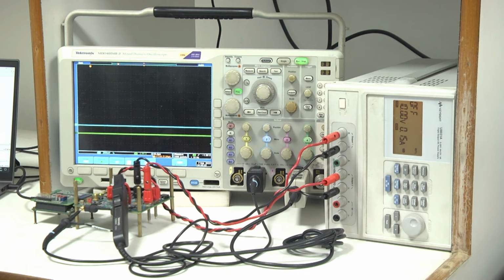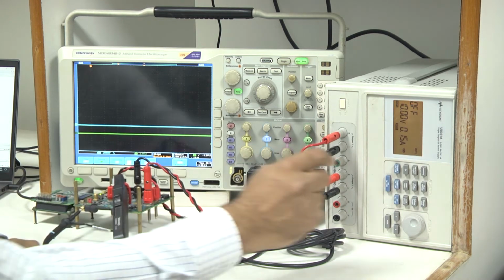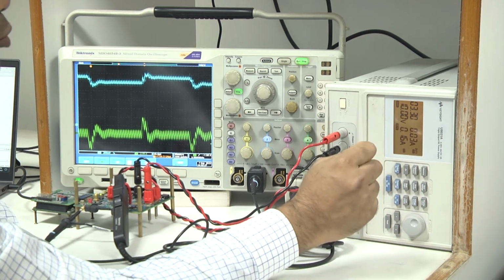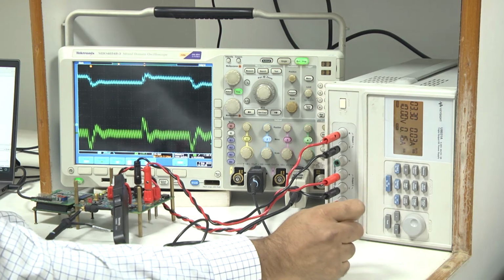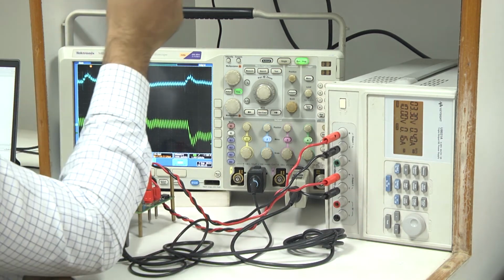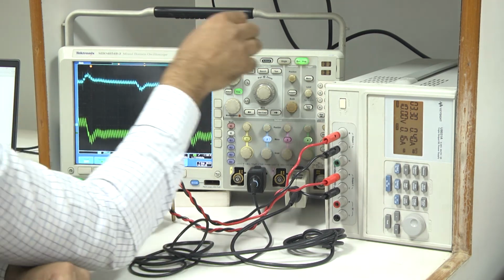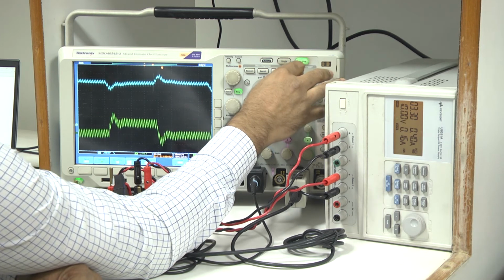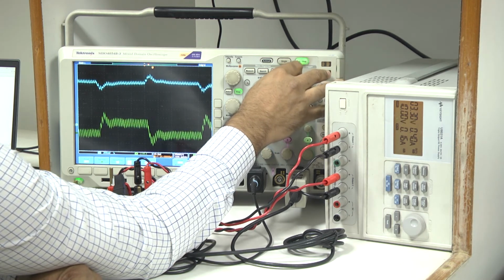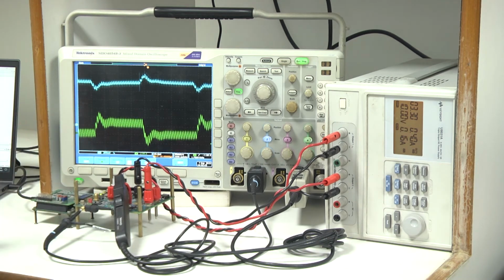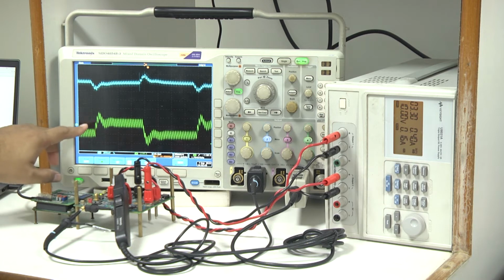So, this code is running. Now, we are turning on the power supply, 3.3 volt is the input, and first, let us say we are making a load transient. This is a load transient where we are changing the load current. Initially the resistance was 13.5 ohm. Now, we have made a load step transient.